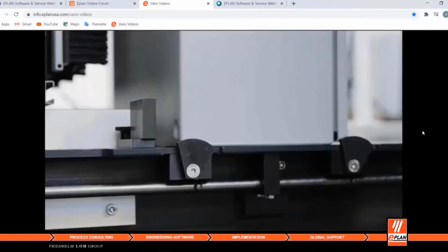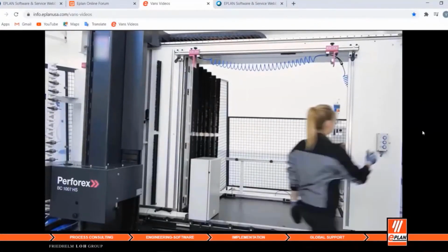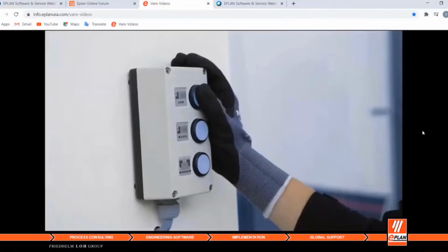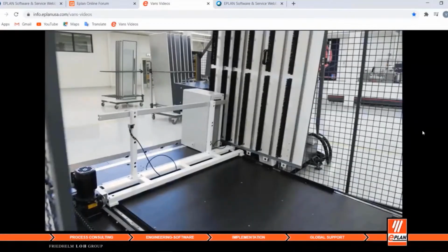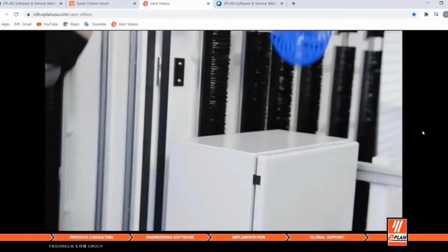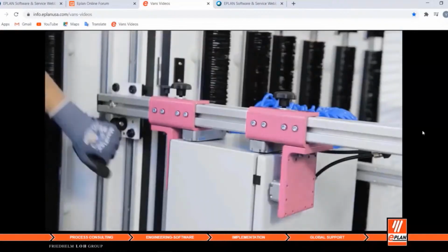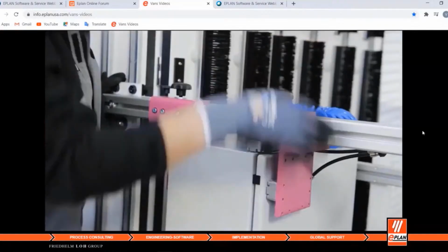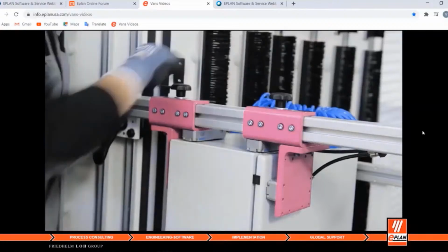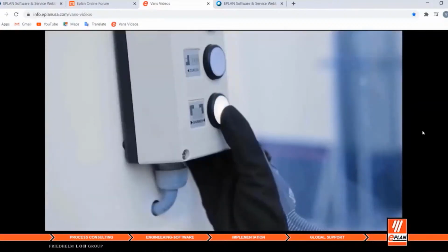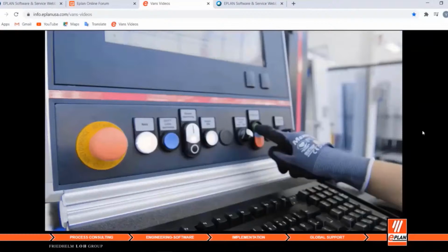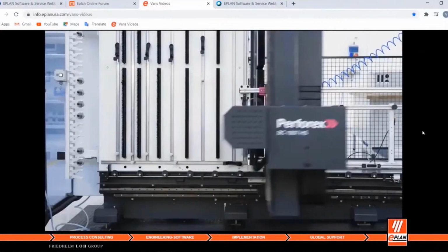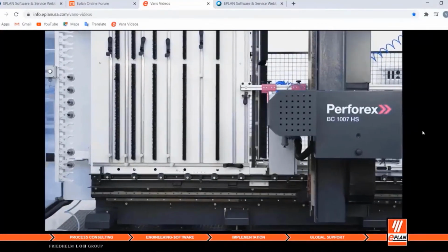And so the 0 points on the machine are hard mechanical 0 points, and we see the motorized depth control bringing the workpiece up to the 0 point in the Z-axis. Here, all of the clamping systems are very simple and easy to use. So we use Festo pneumatics to really grab onto that workpiece and hold it stable during the machining process.